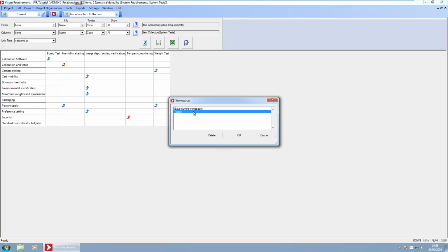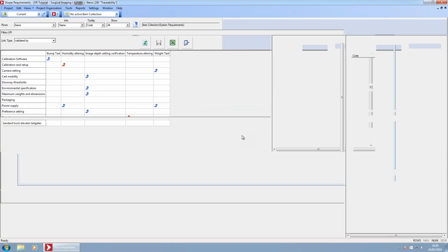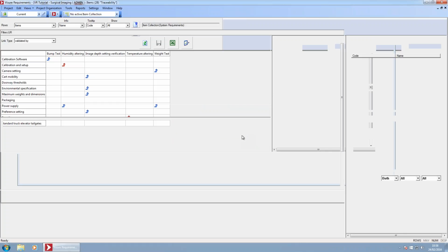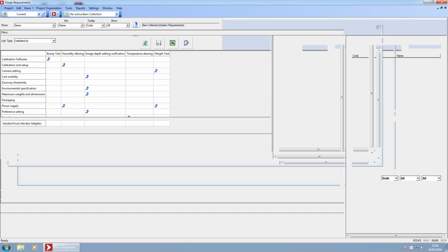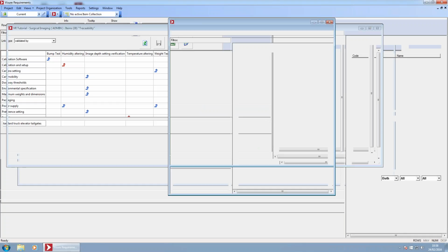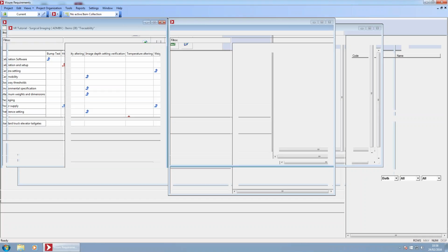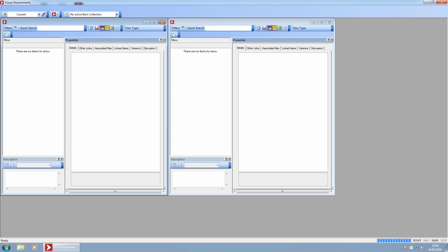Finally, I would like also to show you, we are running out of time, so I will be just finishing. I would like also to show you that we can create a trace in several ways. Just upon element creation, when I create a new element, I can create the element automatically out of an existing one. I can just create the elements afterward and trace them by just using the element properties, or I can even establish traceability by creating a view that is going to contain two types of elements, and just by drag and drop elements from one to another.